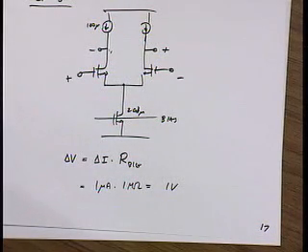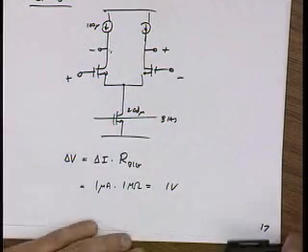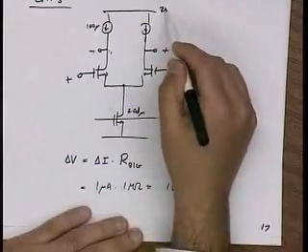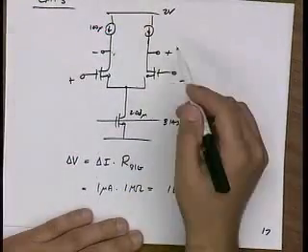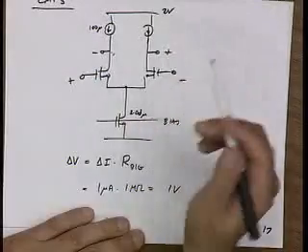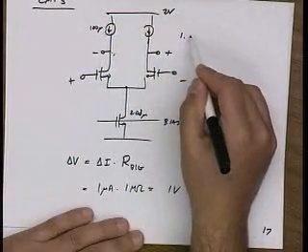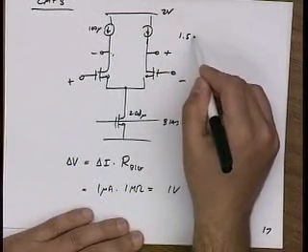It'll cut down on your differential output swing. Yeah. You know, we don't have that much voltage headroom to play with, right? We might have 2 volts here. And maybe if we've designed everything just right, we're getting, let's say, 1.5 volts swing.